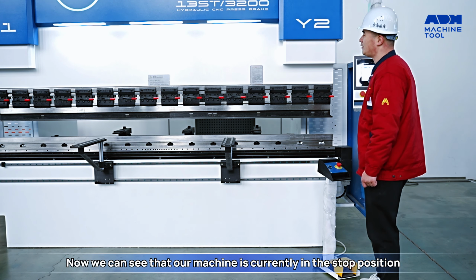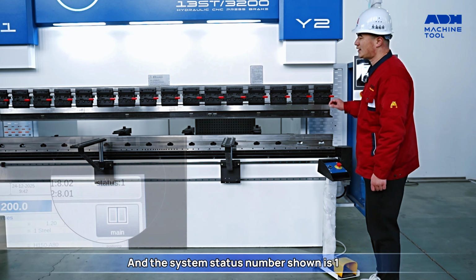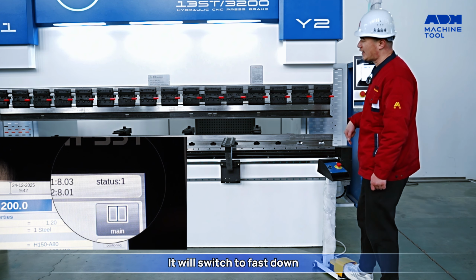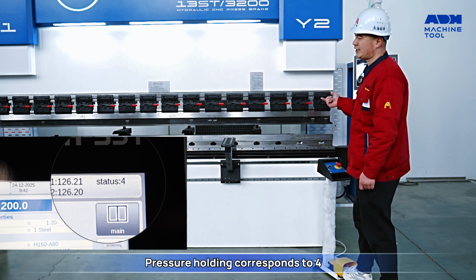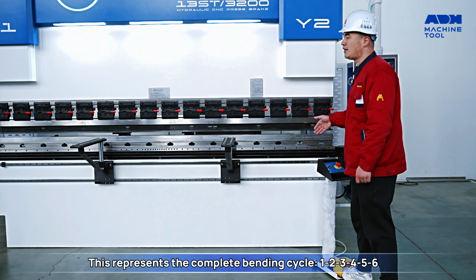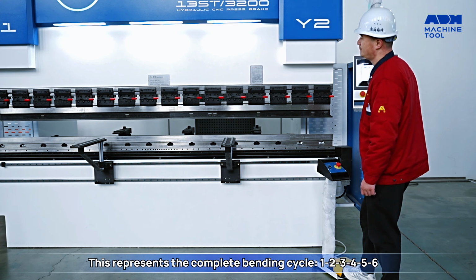Now we can see that our machine is currently in the stop position, and the system status number shown is 1. After stepping on the foot pedal, it will switch to fast down. Fast down corresponds to 2. Bending down corresponds to 3. Pressure holding corresponds to 4. 5 is decompression. 6 is return. This represents the complete bending cycle. 1, 2, 3, 4, 5, 6.